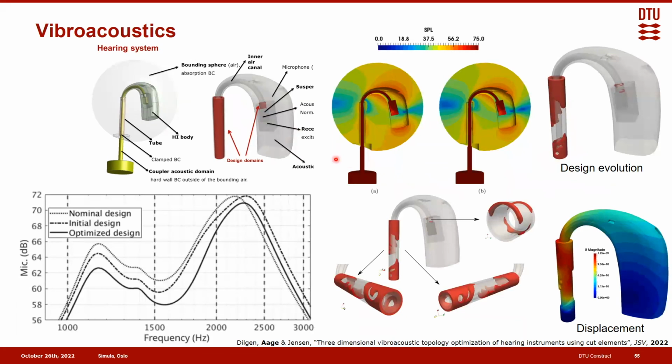So this is actually quite a big numerical model. It has some million elements and we need to solve both physics on top of each other. So it's a nasty problem and it's time and money, meaning that the discretized system is indefinite, meaning that all the nice multi-grid preconditioning stuff doesn't work. You have to do other stuff.